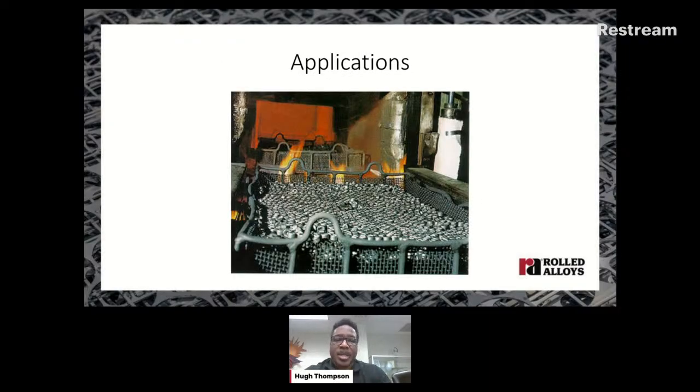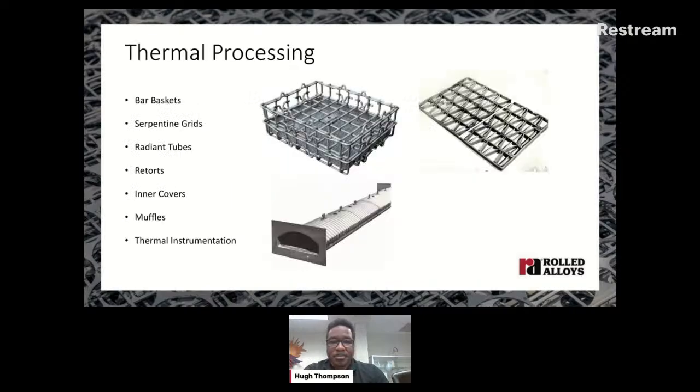So before we conclude today, I'd just like to discuss some applications that really commonly use these heat-resistant alloys. The first is going to be the thermal processing industries. Oftentimes, you'll see heat-resistant alloys for bar baskets, serpentine grids, radiant tubes and retorts, as well as muffles.